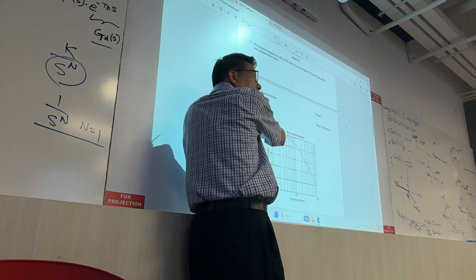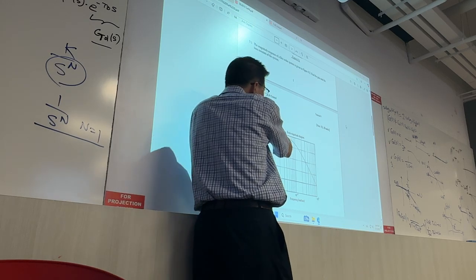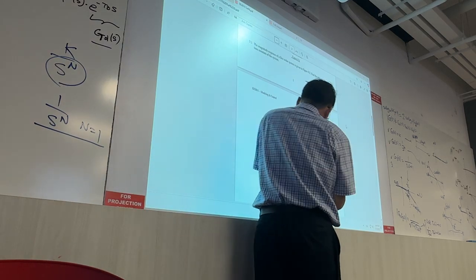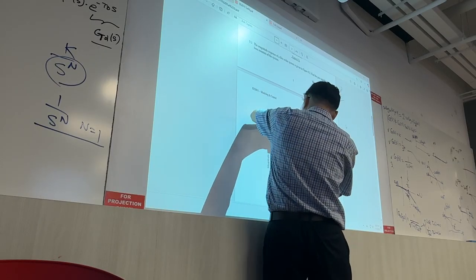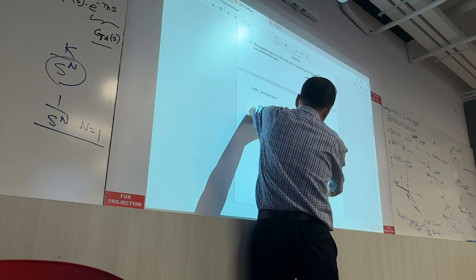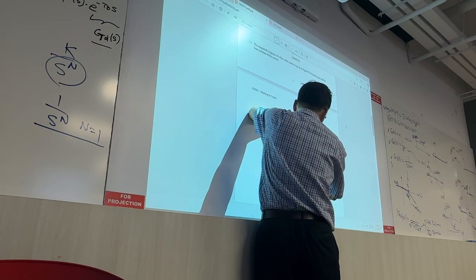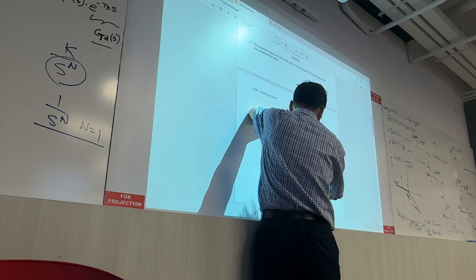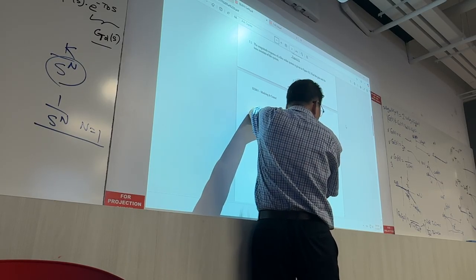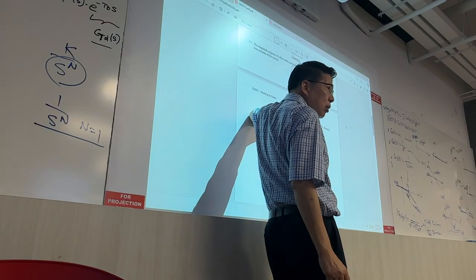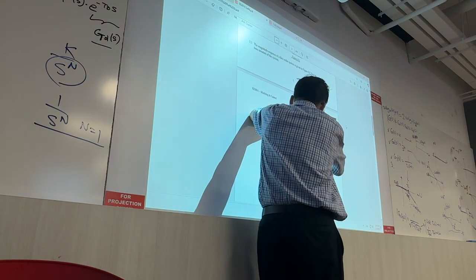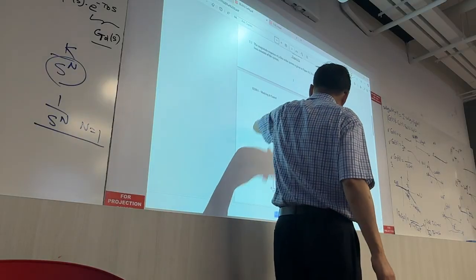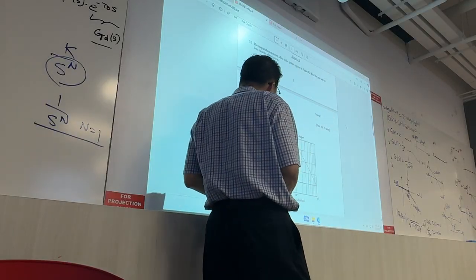That means K is 10, right? On the right, you can see that in 1 decade, it changes about 20 decibels. From here, you fit the slope minus 20 dB per decade. So this should be a first order system, I mean, a first order basic factor in the denominator.